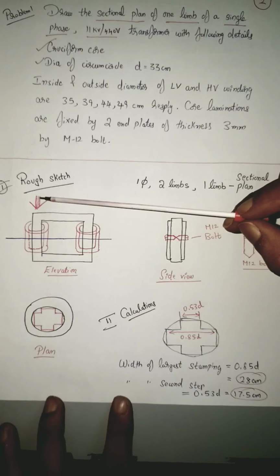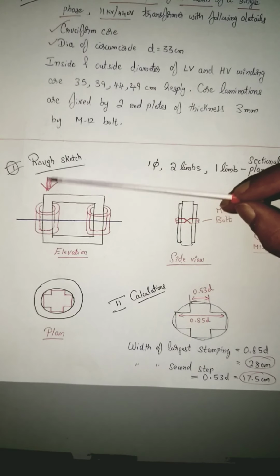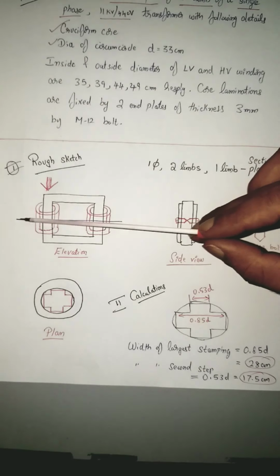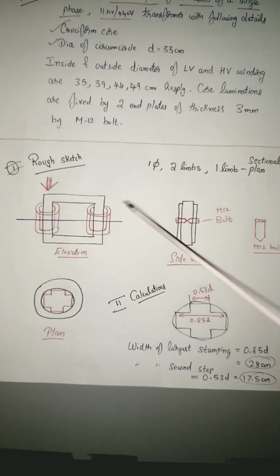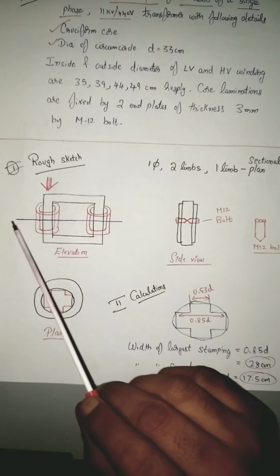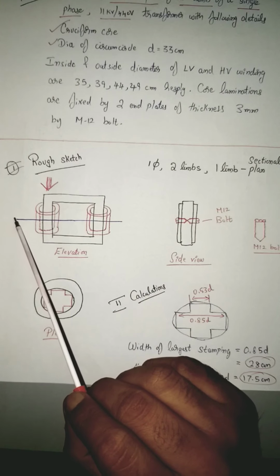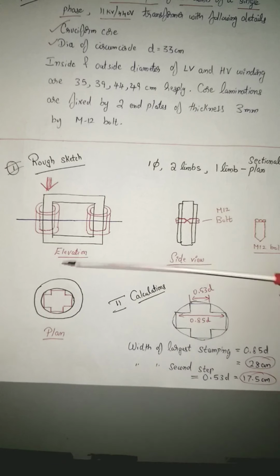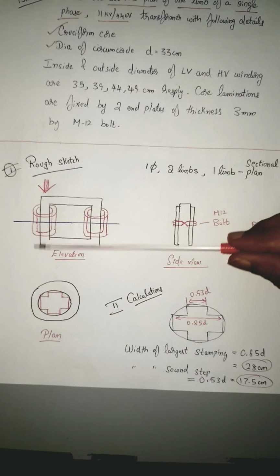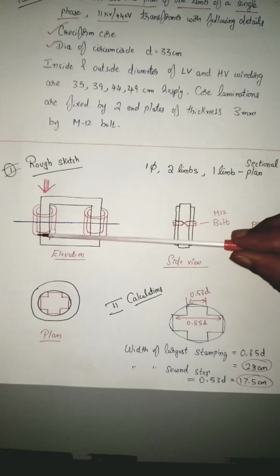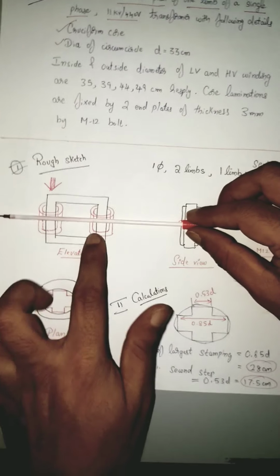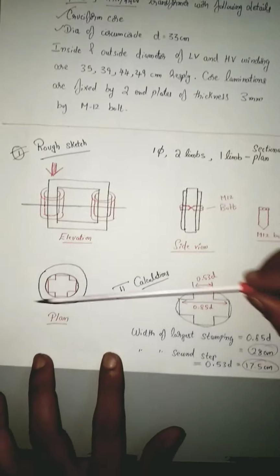So here if you imagine from the top, if you see this from the top, this is how it looks. And remember, I have drawn a blue line here in between, that means it is cut. Just imagine this particular drawing is cut at this particular place. If it is cut, whatever you are seeing in the lower half part, you are supposed to draw, and that too for only one limb. Only one limb you should consider. And from the top, if this is cut, if it is sectionalized, this portion is to be shown now from the top, and this is how it looks.